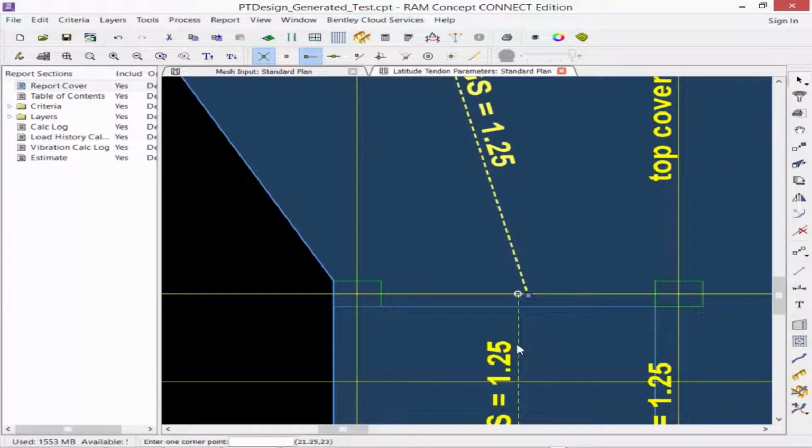Then I'm going to keep adjusting as necessary. So I'm going to select this polyline now, and here I can use my stretch tool. And I'm going to stretch it forward. And then I'm going to also stretch them back to their intersection points.